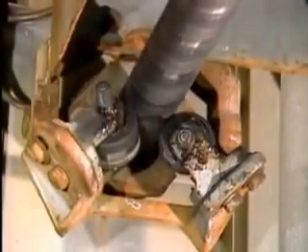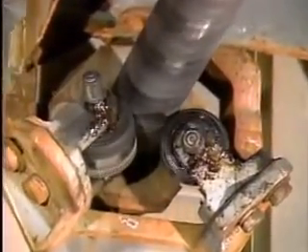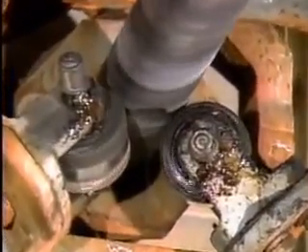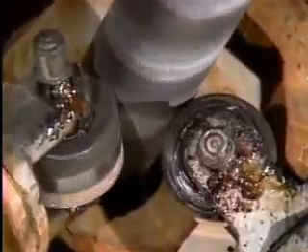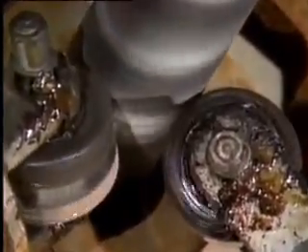The rollers support a device that's used to clean the tubes inside an operating boiler. Heat from the boiler is transmitted to the rollers in the grease. Grease made with ordinary thickeners would melt and drip out of the bearings, but the bentonite resists high temperatures, so it keeps the grease from melting. Many substances that are added to lubricants are liquids rather than solids.